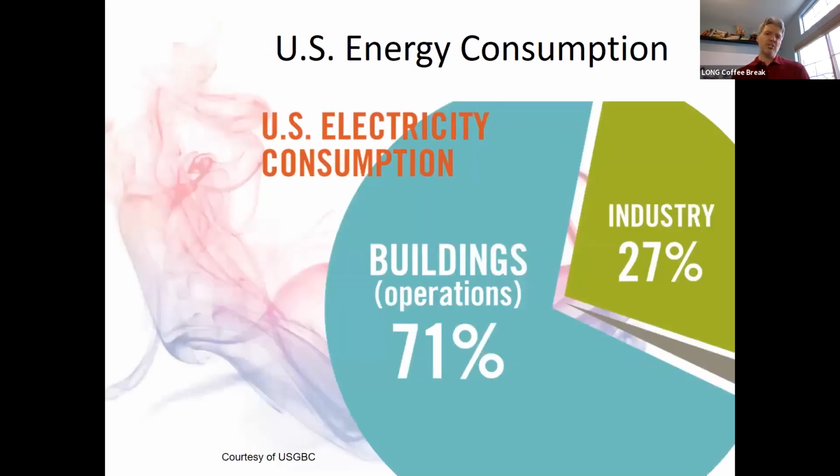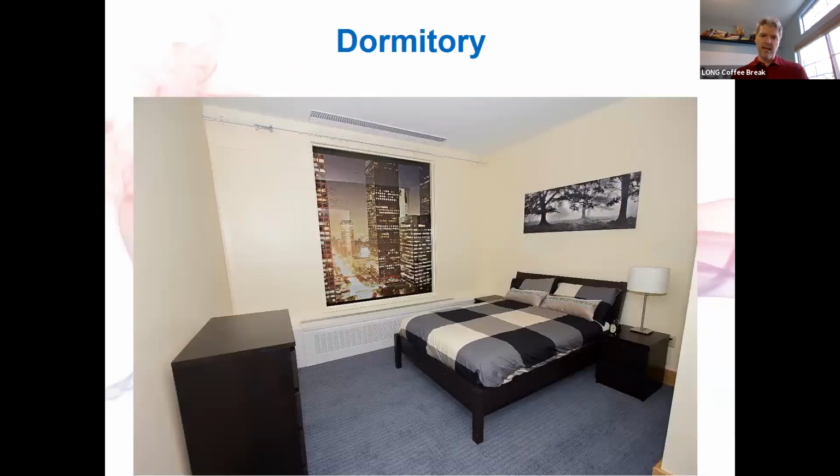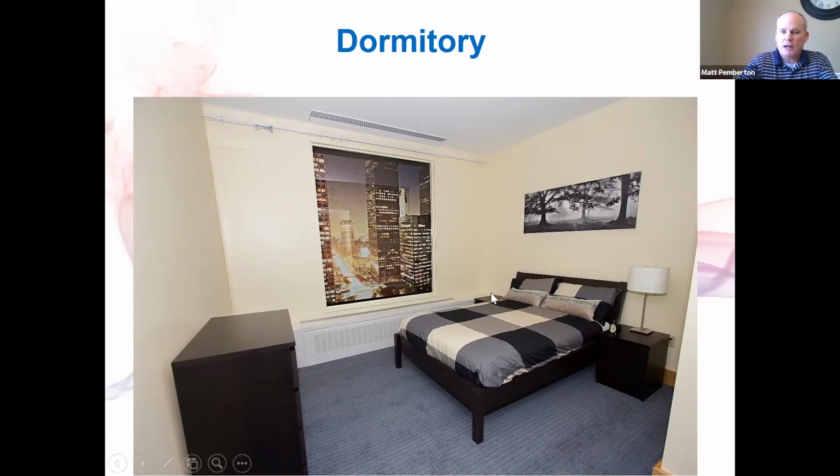How has the technology changed to what we see from active chilled beams today? Sure. So here's that picture of that one along the perimeter. As I mentioned, we don't see a lot of new installations designing induction units, but we do a lot of replacements. As you mentioned, the old technology behind that enclosure there in the corner, if you can see it, in the front is a louvered panel where your air is being induced. And on the top is a louvered area where your supply air is coming from, cooling and heating.